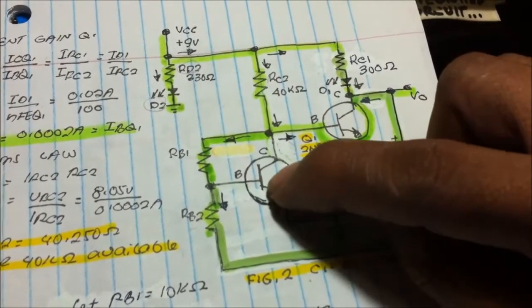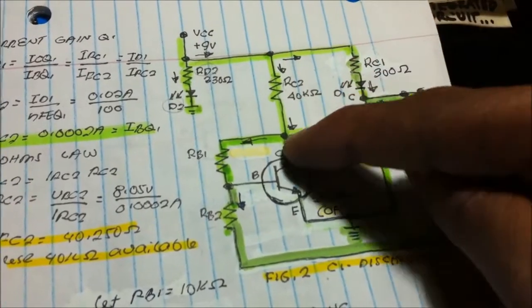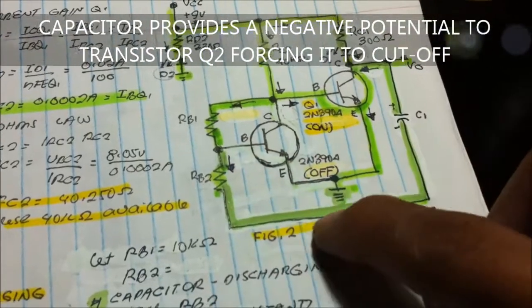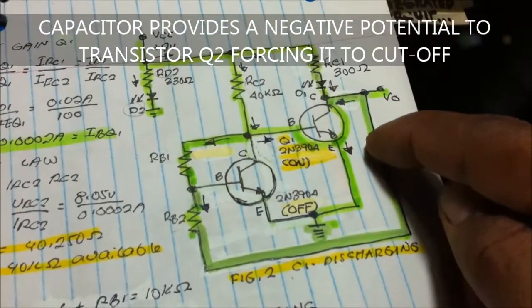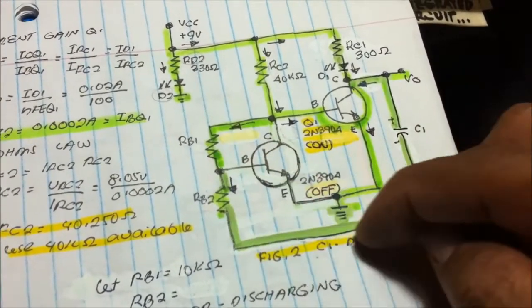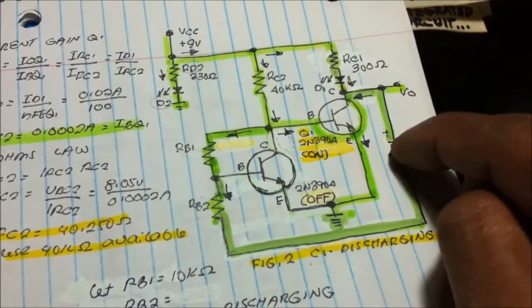What happened here is this is cut off, because at this state current flows into here, into the base, into the other end, RB1, RB2, and to the capacitor, to the output, this feedback path of the capacitor. This is now the controlling component.